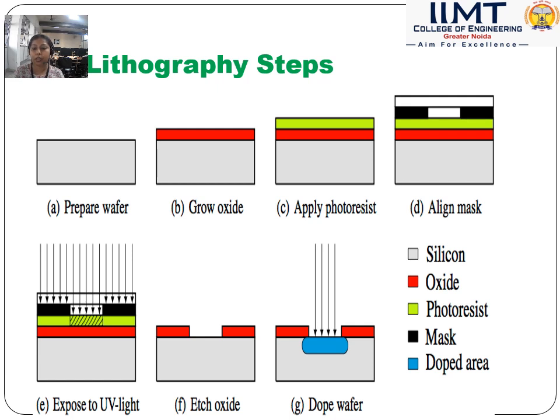For that, we use metallurgical grade silicon, which is converted into electronic grade silicon using a purification process. From electronic grade silicon, we obtain single crystal using the CZ process. After the CZ process, we use different cleaning and polishing techniques to finally obtain the wafer.